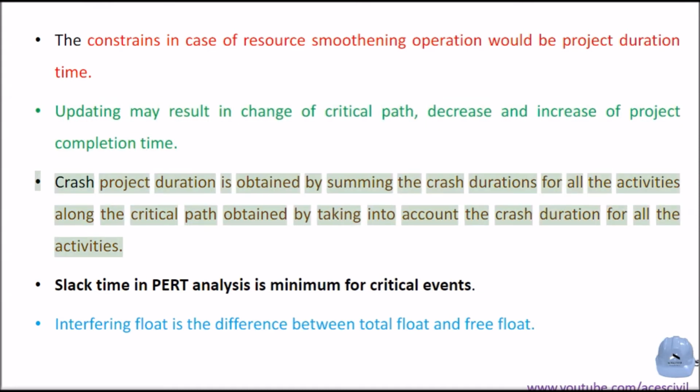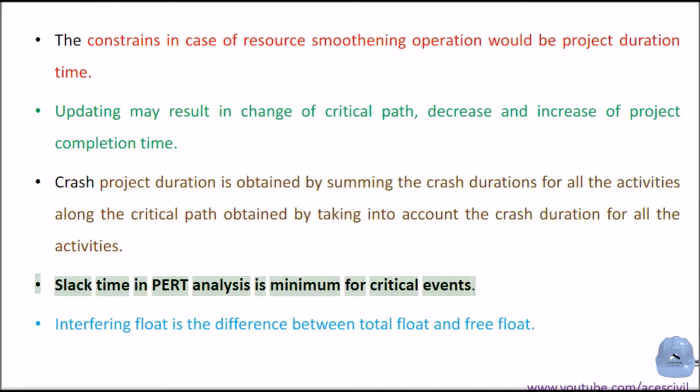Crash project duration is obtained by summing the crash durations for all the activities along the critical path, taking into account the crash duration for all the activities. Slack time in PERT analysis is minimum for critical events. Interfering float is the difference between total float and free float.